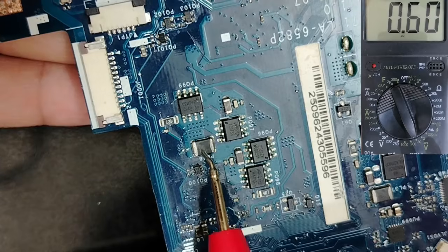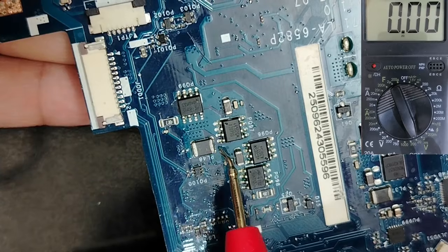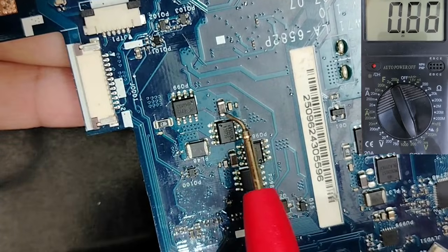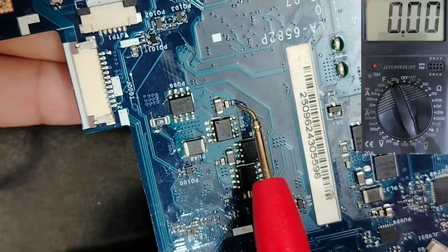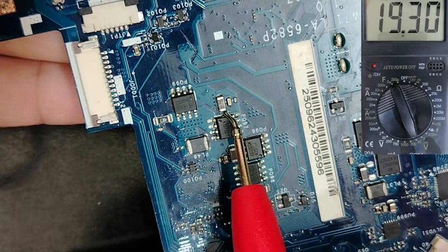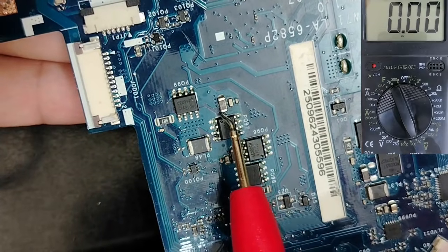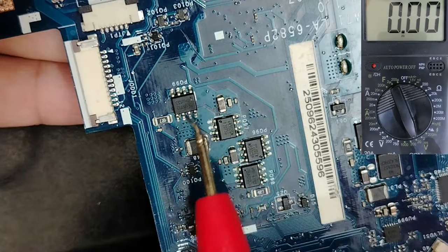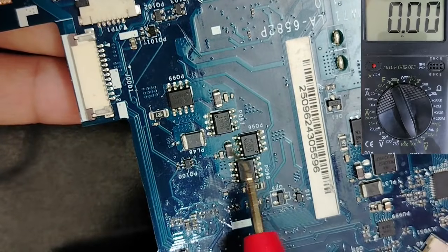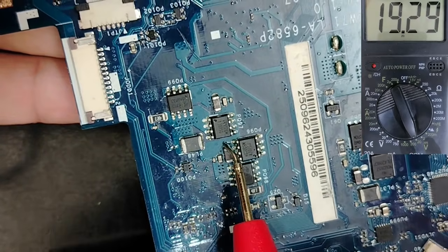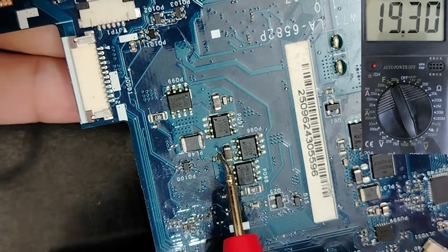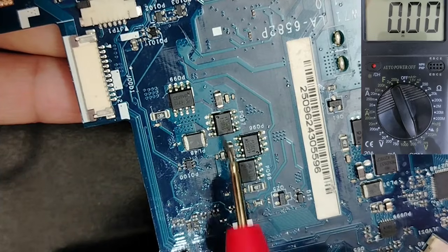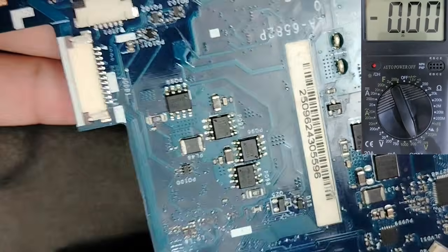And this inductor, by the way, is for the input. We're going to find 19 volt, as you can see. This is the input, and we have 3 ceramic capacitors as input for this 5 volt channel, and we have 3 other capacitors for the 3.3 volt channel, as you can see. Okay, so we have the input inductor, 3 capacitors, and 2 MOSFETs for this channel.